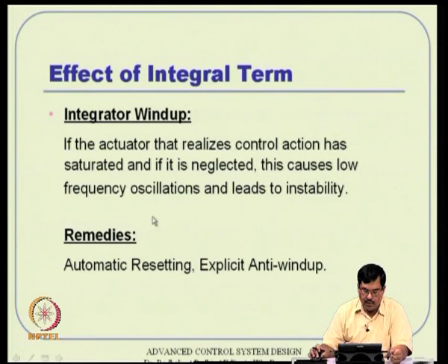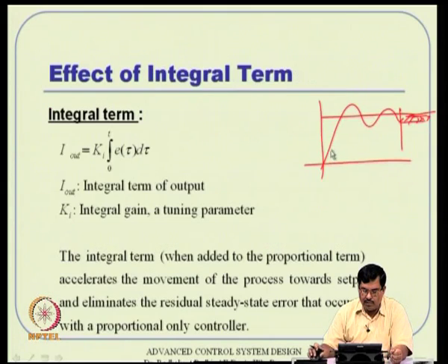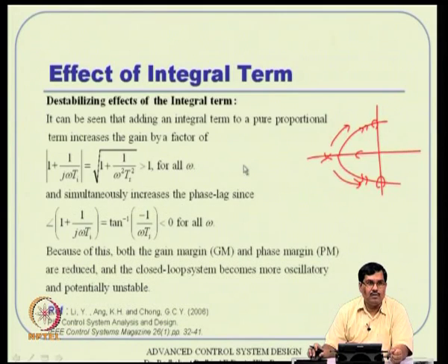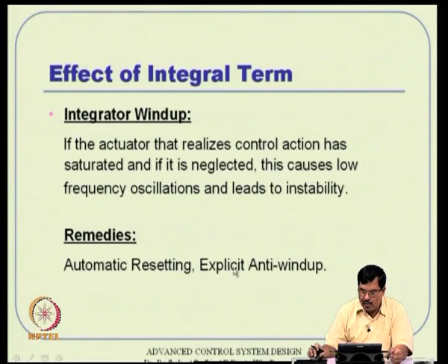The remedy for that is the periodic resetting of the integral value, because see this particular term, you start from t0 and keep on resetting the t0. So, this integral value starts again from t0 to t0, that means again it becomes 0. The integral component is periodically set to 0. That is one remedy, and there are explicit anti wind-up logics also. People have devoted a lot of attention to this particular problem, even on nonlinear systems. So, there are anti wind-up logics available in an explicit manner.